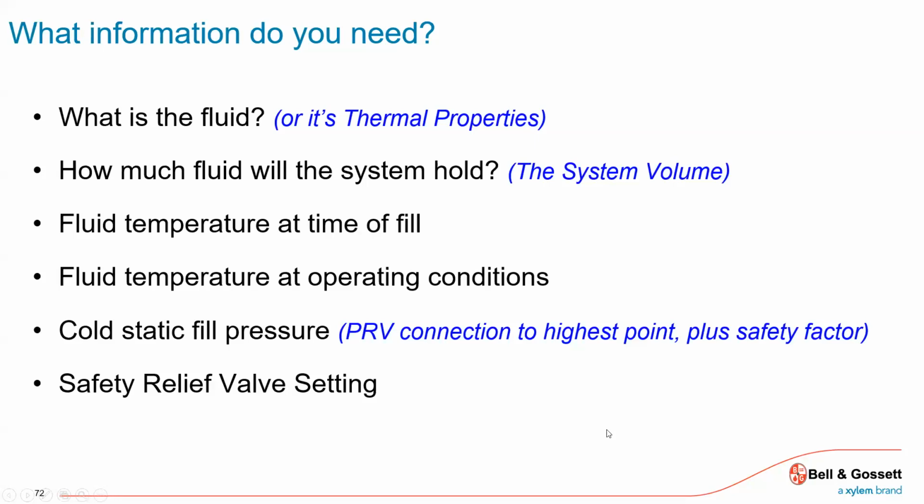Fluid temperature at time of fill, fluid temperature at operating. So I fill it with the system cold. That's pretty standard, industry standard. 50 degrees, 40 degrees street water, 50 degrees street water. Fluid temperature at operating. Okay, what's my aquastat set for? 180, 200, 160. What is it?